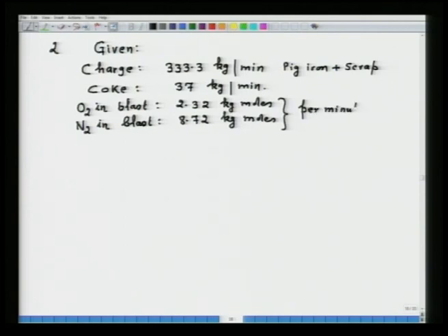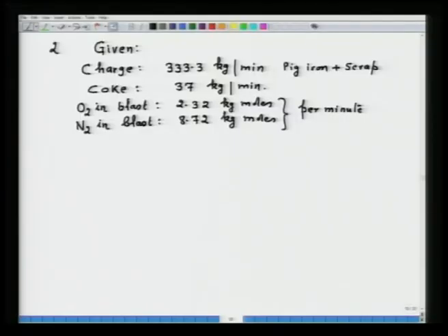and also the volume flow rate which was given at 313 Kelvin I converted, and these values are at 1 atmosphere and 273 Kelvin. So, you can choose the basis the way you like, you can calculate on per hour basis or 2 hour basis, whatever you do. The only thing I wanted to tell is that you should be consistent in your calculation.